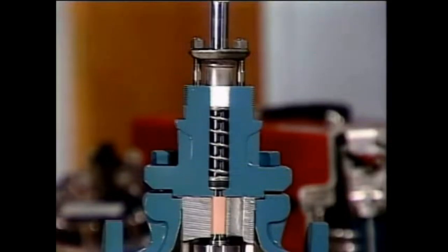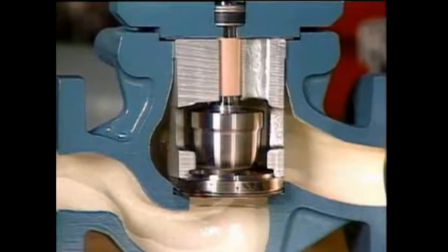For example, control valves, like this one, generally include guides that align the valve stem and disc with the valve seat. These guides help ensure precise control when the valve is opened and closed. The upper stem guide on this valve is housed above the packing inside this part of the packing assembly. This is the lower guide, which is held in place by this part of the valve called a cage.